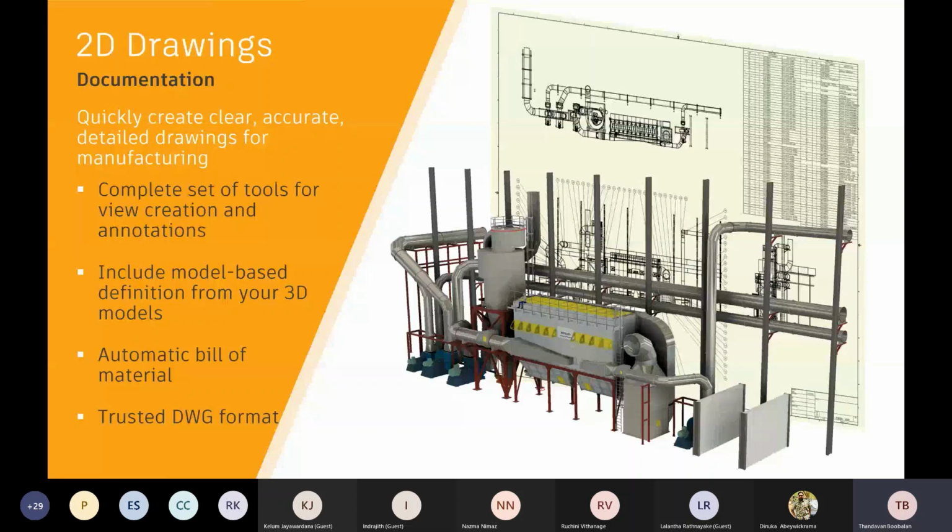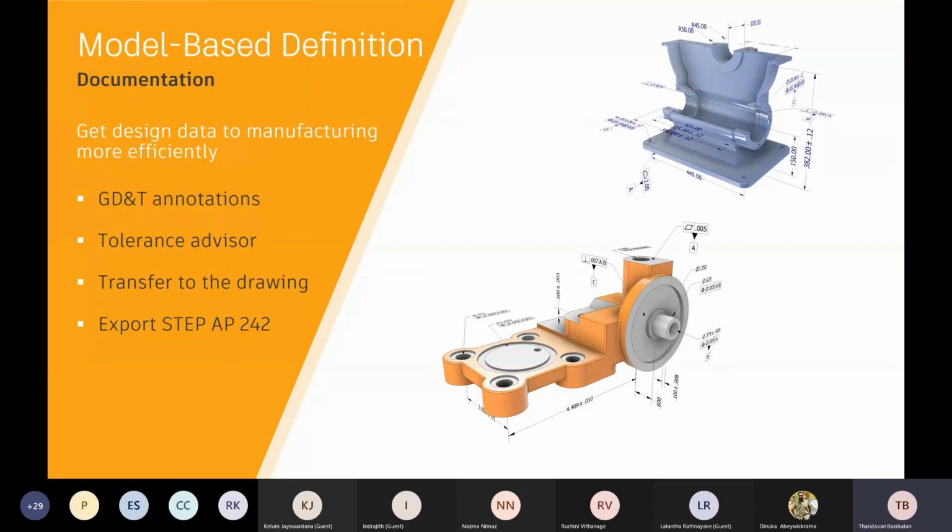Many of our clients, or even the manufacturing unit, might have a plain AutoCAD software. So if you want to communicate with the manufacturing unit and give the AutoCAD native file format, yes, in Inventor itself you can create AutoCAD sheets with all the views, part list, hole table list, and BOM, and all of this information can be placed on your sheet, and you can send it to a manufacturing unit. Yes, that's the interoperability we have.